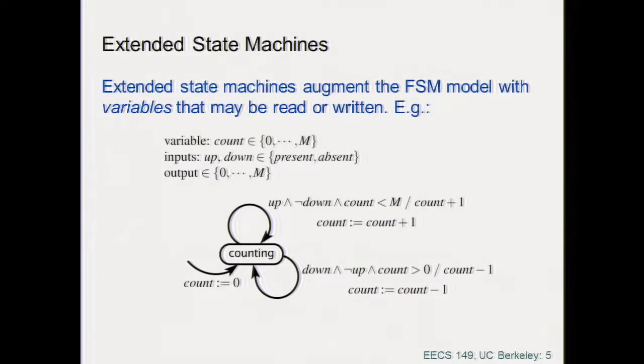Here it goes, right? And so there are two self loops. One which says, okay, the counter goes up by one, so there is a new car coming in. And one goes the other direction, a car leaves, so you have a self loop, and the count is decreased by one. Now, notice that the output at this point in time is no longer a pure signal. It's an integer, right? Which corresponds to 1, 2, 3, 4, 5, n. And so this one, strictly speaking, is not a pure finite state machine, but a finite state machine whose output is a natural number, okay?